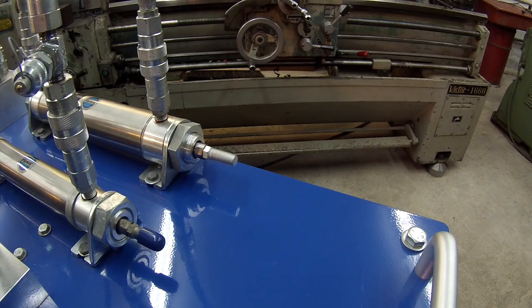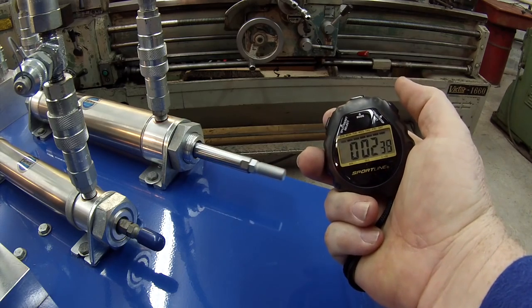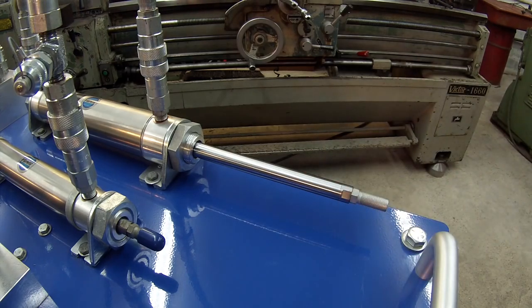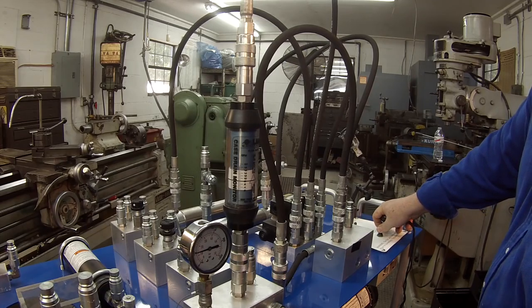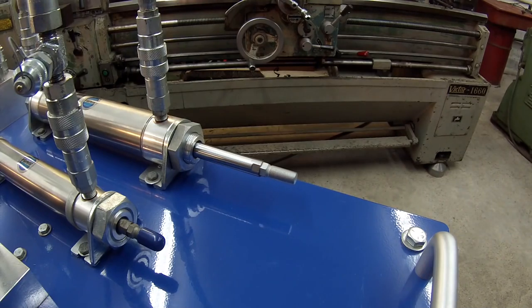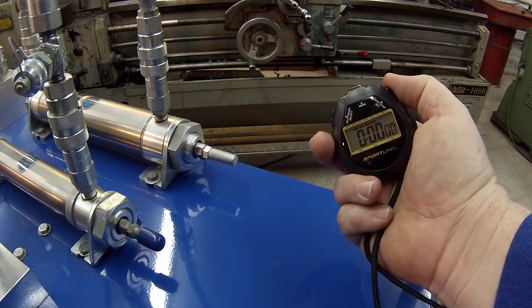Alright, so what we're going to do is, see over here, you see the flow is right at about 1.8 gallons a minute, 1.6, something like that. So what I'm going to do is cut that down to about in half, to a little less than 1 gallon a minute, something like that. And then we're going to time this coming back out, and it should be about half. It may vary just a little bit because the oil is kind of cold, but we'll give it the old college try here.